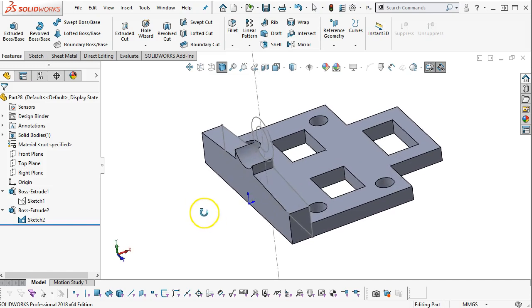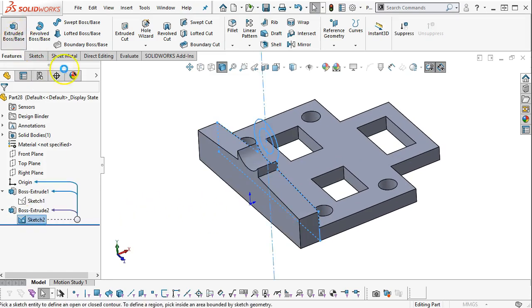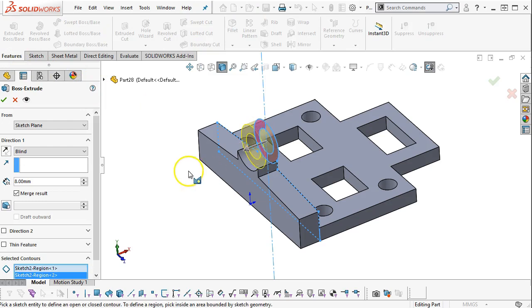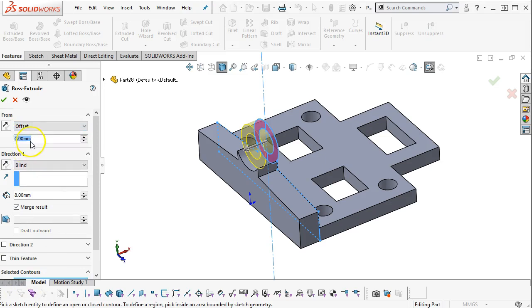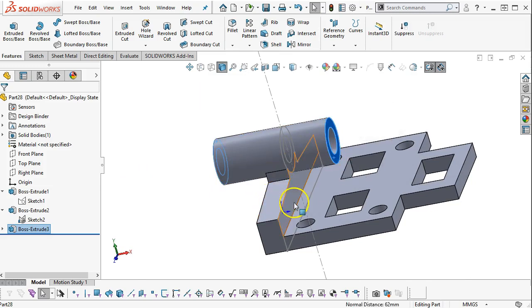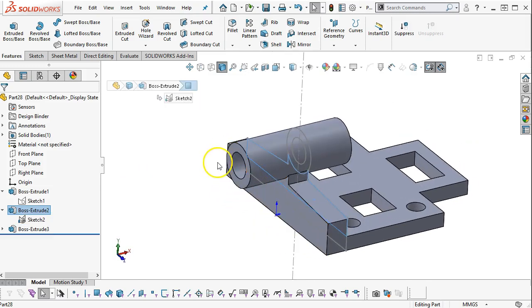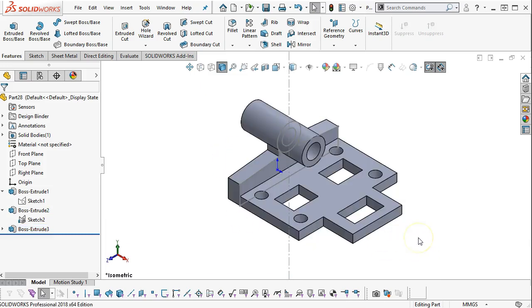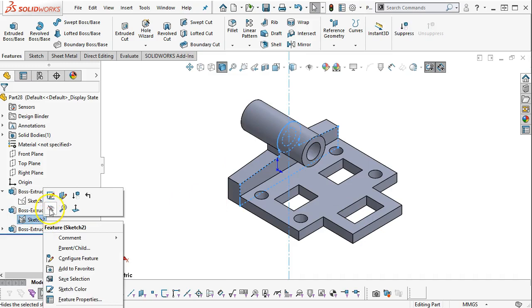So a couple of ways that we could do that is with the math. All right, so pretty much the ID. So if I were to offset this back 37 millimeters and then give it a distance of 62, well, that basically takes care of the math, except I got to get it going in the right direction. All right, so that gives it my shape. We'll double check the number. All right, so 62, 37. All right, so went the right way. Those all look pretty good. And then we can go ahead and hide that sketch.